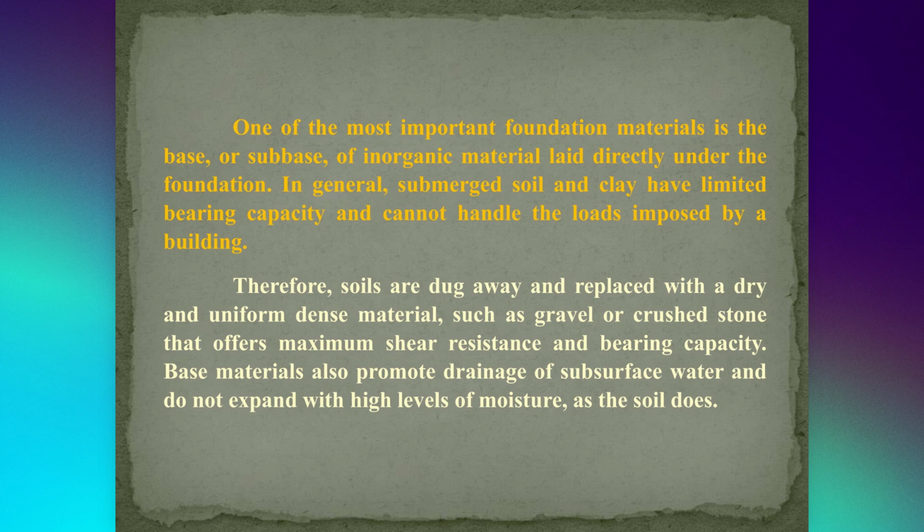One of the most important foundation materials is the base or subbase of inorganic material laid directly under the foundation. In general, submerged soil and clay have limited bearing capacity and cannot handle the loads imposed by a building. Therefore, soils are dug away and replaced with a dry and uniform dense material, such as gravel or crushed stone, that offers maximum shear resistance and bearing capacity. Base materials also promote drainage of subsurface water and do not expand with high levels of moisture, as the soil does.